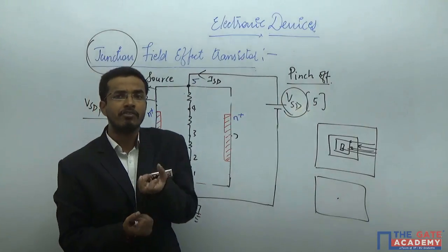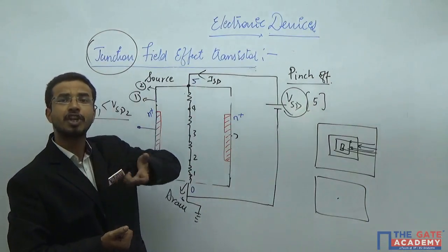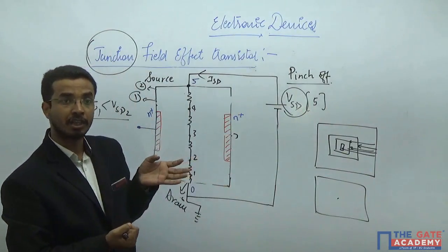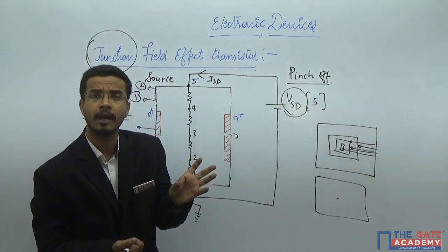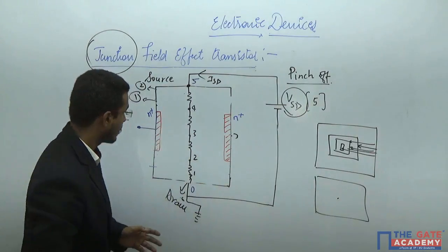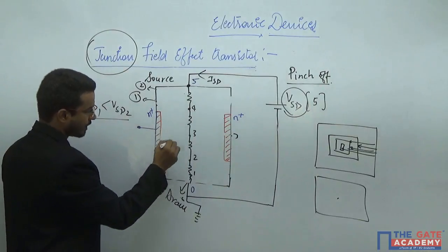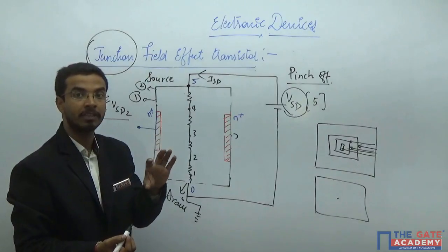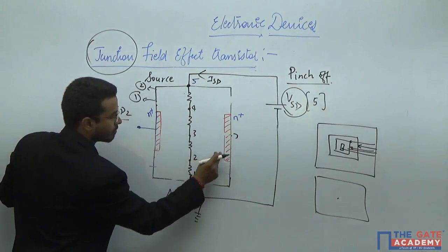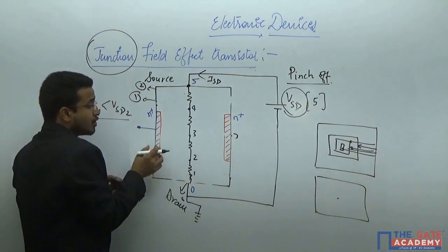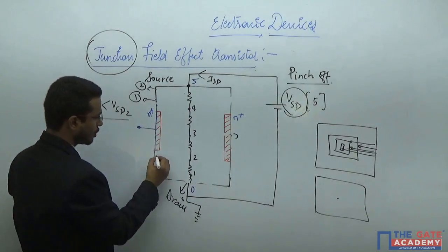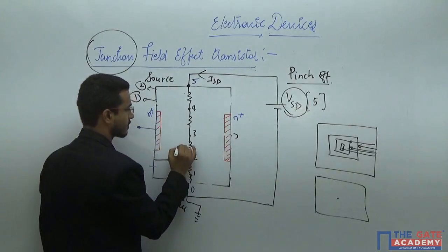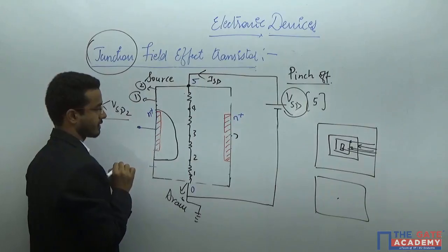And you know, if the reverse bias voltage across the junction is continuously changing, the depletion width shape will also vary. Where the reverse bias voltage is high, the depletion width will be high. Now, instead of sharp shapes like that, you will get modulation in the shape of the depletion width. That means here at this bottom surface toward the drain side, you have more reverse bias, and the upper surface has less reverse bias, like this.